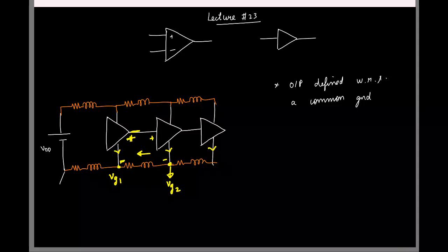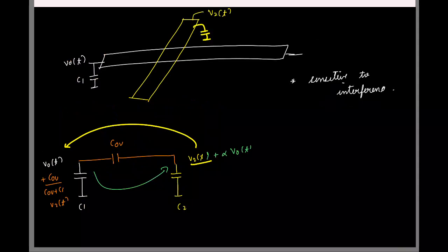I should have a separate second line. Just like how I have a local single-ended output, now I can have two lines locally and say my output is defined with respect to those two lines, right? So that's the idea. So now instead of having one line locally, you have two lines and you say your signal is the difference between these two. That's all. Okay. So this I will call VO positive or VO plus and VO minus of t. Okay. And this is called the differential signaling.